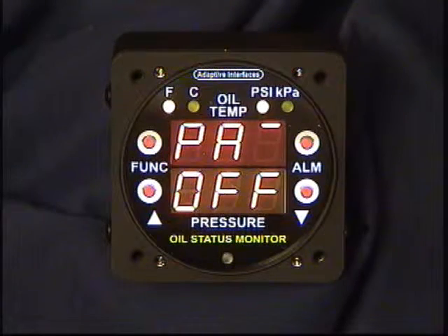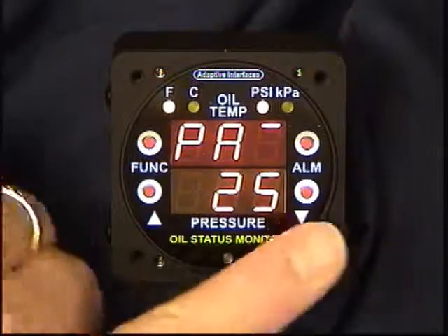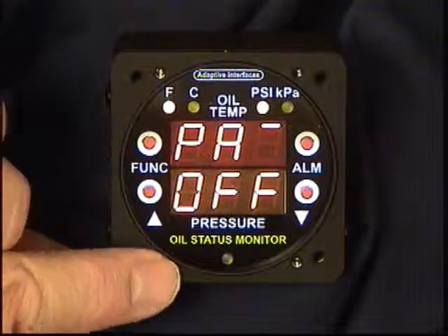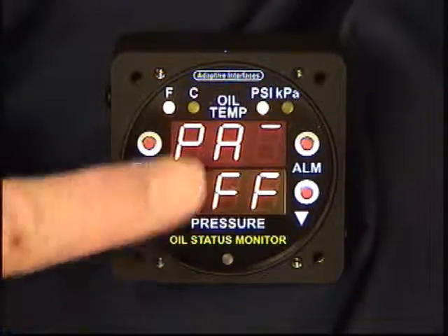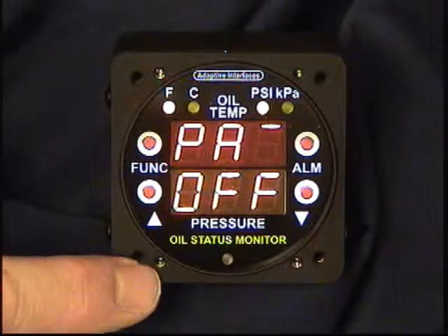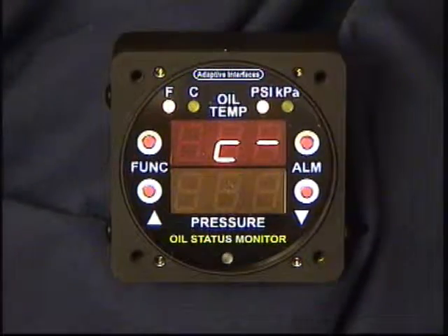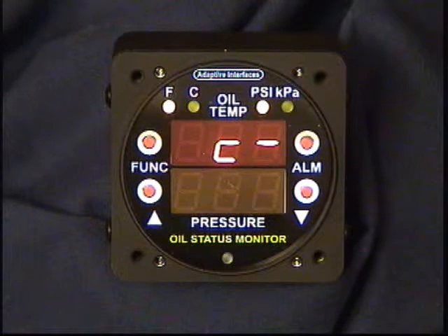The next alarm is a high pressure alarm setting. Again, it can be set in 5 psi units. And again, in this case, if the pressure exceeded the alarm setting, the instrument would go into an alarm condition. Next function available is the single return symbol, which is a return 1 menu level. This would bring the instrument back into menu level 1.